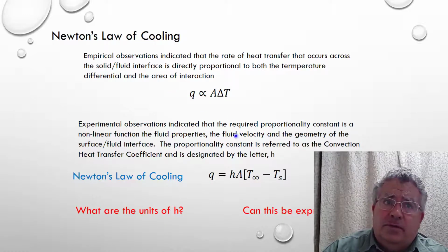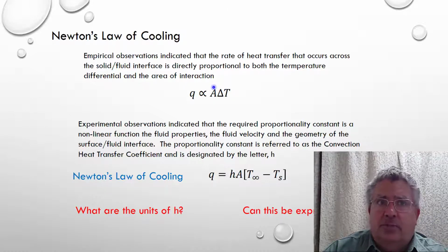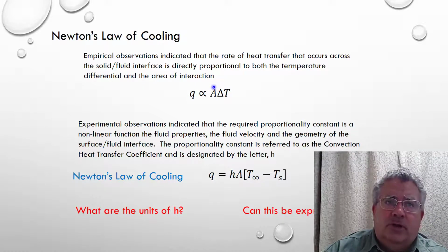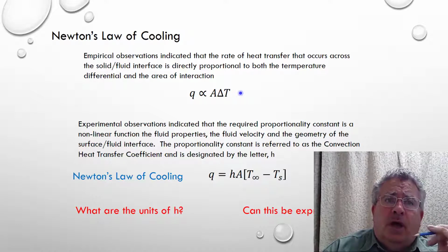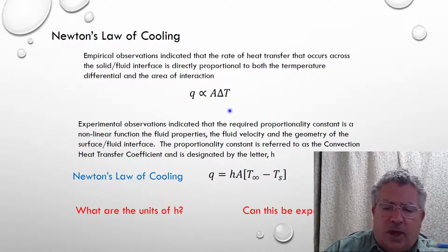So in this case, again, it's an empirical observation where the rate of heat transfer is proportional to the area. Double the area, you double the rate of heat transfer, and it's proportional to the delta T. So if you double the temperature difference between the surface and the fluid, you will double the rate of heat transfer.